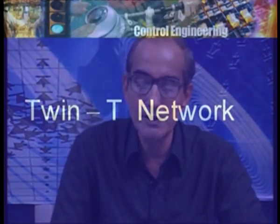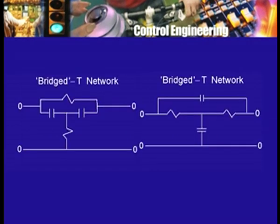It is possible to think of one more network which is a little more complicated, which is called a twin T network. A T network is what this looks like, a T, right? This capacitor arm, another capacitor arm, and a resistor arm, this is a T, this is another T. Now, you can connect these two T's in parallel, so to speak, at the input terminals, in parallel at the output terminals, and you get a twin T network. You can find out what will be the transfer function of a twin T network. Of course, it will be a little more complicated, it will involve more calculation and so on. But you should try this out on your own before you look up any expressions which are given in your textbook.